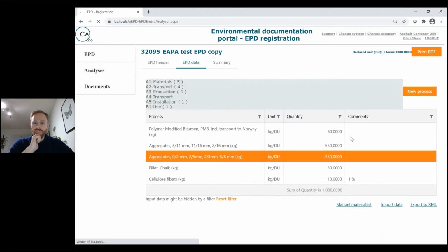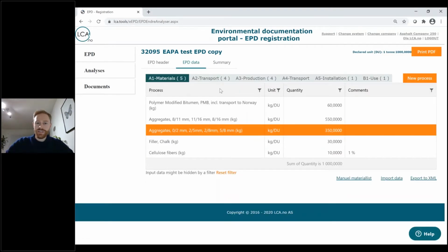asphalt recipe. And I could also mention here again, as Geir said, that the users cannot modify the background data here, the emission factors, but they work with specific input data for all the relevant stages as asphalt producers. And the database is mainly pre-calculated values, so it's not a full LCA database as used in LCA software. So the amount of data points is also then less. So it's only predefined data following the indicators of EN 15804, which also then makes it possible to implement EPDs